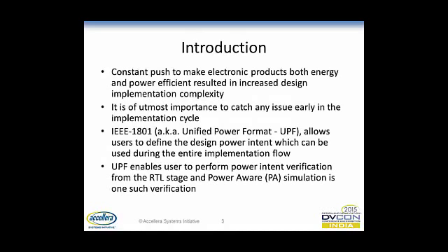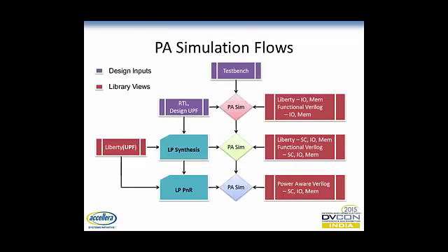IEEE 1801, also known as UPF, allows the user to define power intent, which can be used during the entire implementation flow. And using this UPF, one can perform the power-aware simulation right from the RTL stage. Power-aware simulation is one of the ways to verify your dynamic power sequencing and some of the power related issues, apart from static rule checks, for which there are other tools. So my focus will be on the power simulation.